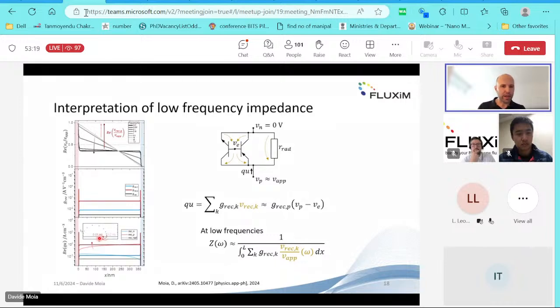Okay, this is all nice, and it allows us to understand not only how interfacial recombination may have a frequency dependence, but also how bulk recombination may have a frequency dependence. But all of this is assuming that ions only are changing the electrostatic potential in the device. But what happens if we apply a large enough perturbation that electrons and holes are also large in concentration?